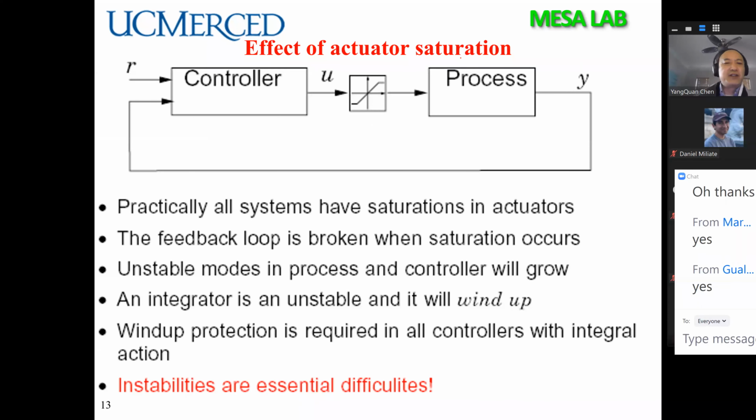So here is the first most important point. It's new to all of you, so listen carefully. In here you have integration, like KP, KI, KD or whatever. If you have integration inside your controller, and if you have a saturator, so this is called an actuator saturator, which is always true.